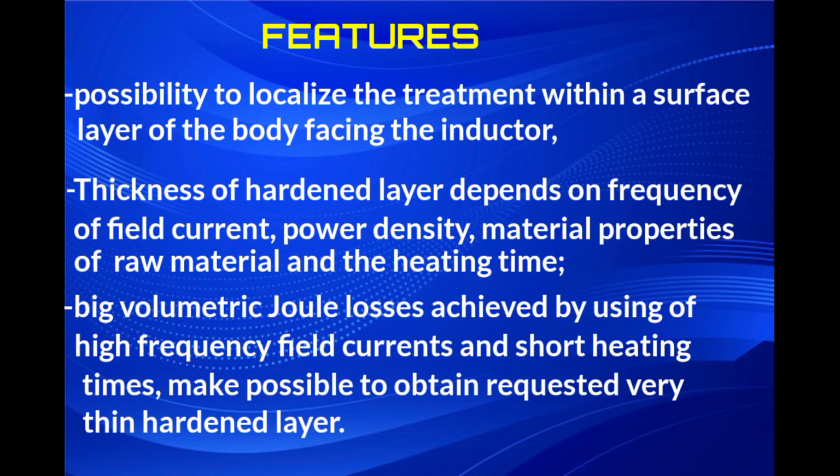Third one is big volumetric joule losses achieved by using high frequency field currents and short heating times, which makes it possible to obtain the requested very thin hardened layer.